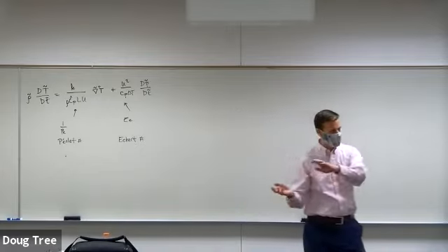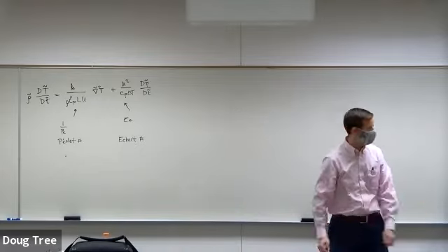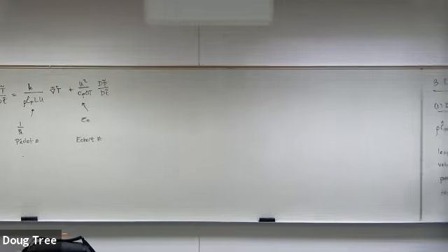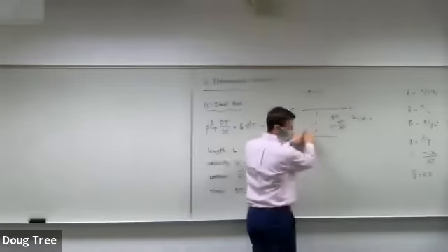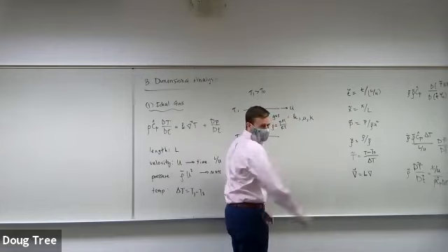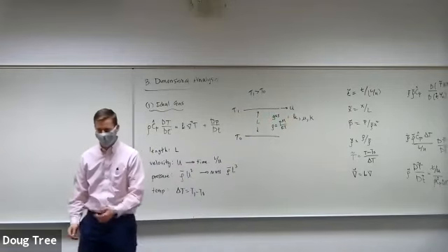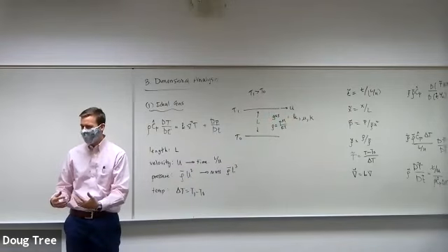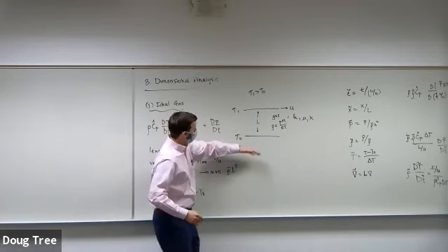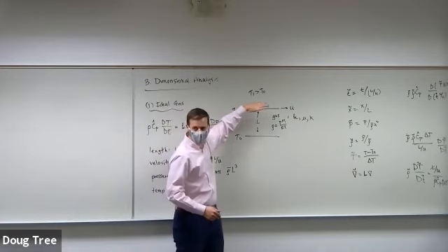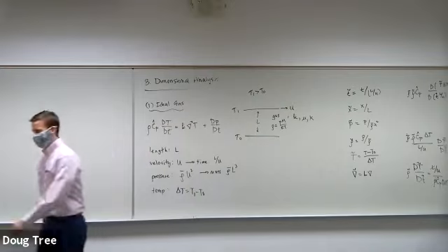So I've got lots of temperature that's flowing around, right? As soon as a little bit of diffusion of temperature happens here, the thing is whipping along, right? As opposed to when the Peclet number is small, then I've got lots of diffusion, and this thing is just kind of creeping along. Okay, so that's a Peclet number.